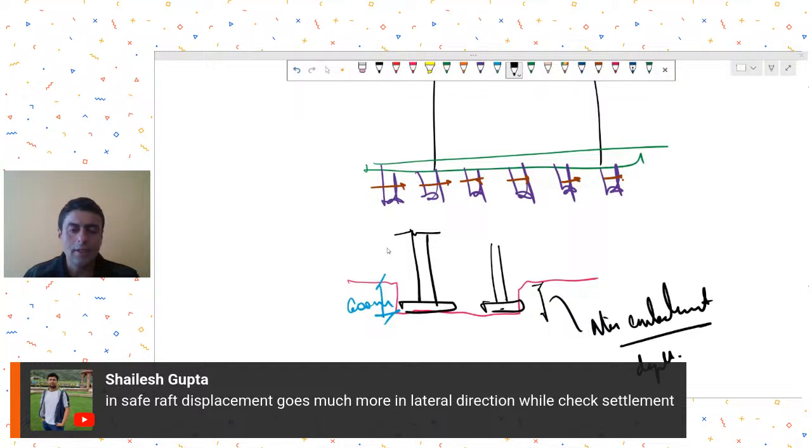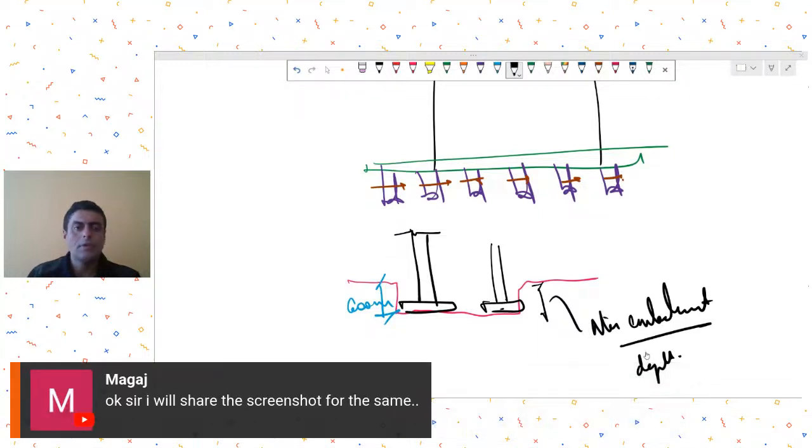So you can assign point or spring stiffness to your node points and assign lateral restraints there. Not even spring supports, I would say just assign lateral restraints in X and Y to your raft corners. Translational restraint. Okay. Anything else?